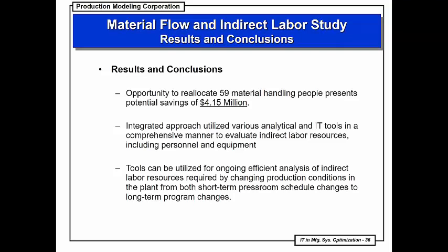We need to know exactly what's happening, and we need the data required to perform either static analysis or dynamic analysis. The static analysis gives you a snapshot of the activity, whereas the dynamic analysis also gives you the interaction between various elements in the facility, and you can track over a period of time how the utilization fluctuates. This can be used to eliminate, reduce or rebalance some of the work content.